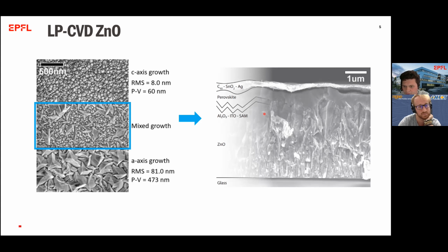So it's very reactive, so we had to interject that. On top of that, we then spin coat a perovskite layer. It's a triple cation, the one that is very heavily used and got famous by the initial paper by Michael Saliba. And you can nicely see how it covers these textures. We finish the device by thermally evaporating C60, depositing tin oxide from ALD, and finally the top electrode, silver.